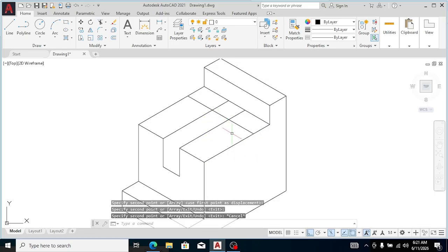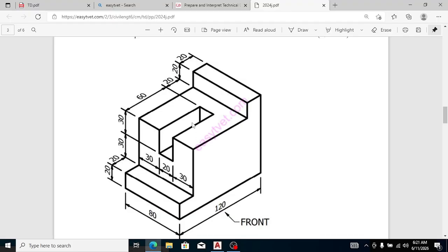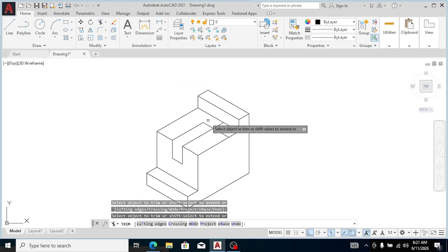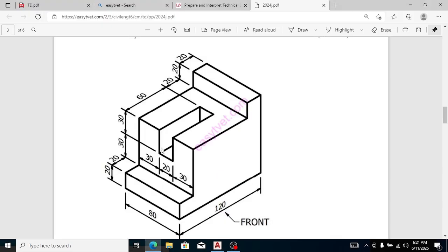Then after that, we make sure the top part of it has something like U, like this one. So I have to delete everything along this line. I will go to my software and take the trim command. I will delete this one, this one, and that one, and then I escape using my keyboard. Now after doing that, I'll remain with this line. Are you seeing this line and the other line?